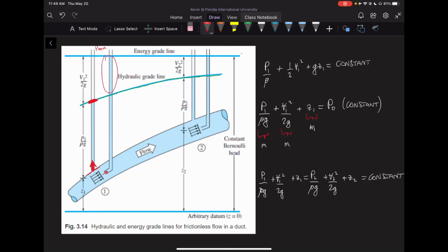So you can see that velocity creates more pressure essentially. It would bring the water up to a higher level. So if we add the two together, we get this whole column here, and we can add the height as well. Same thing at point 2. At point 2, we have a static pressure that is shown by an opening at the top, plus the height of this, plus the velocity effect going all the way to the top.